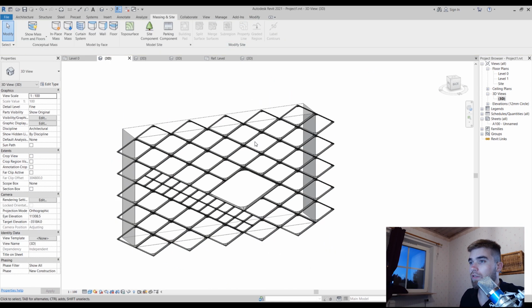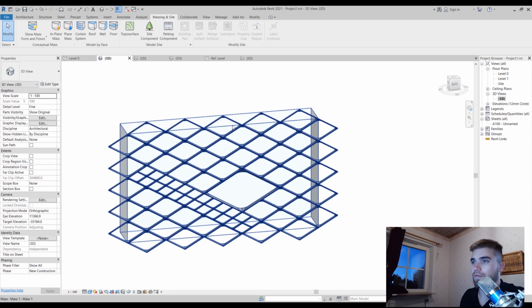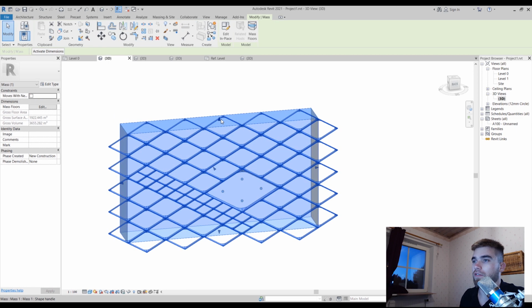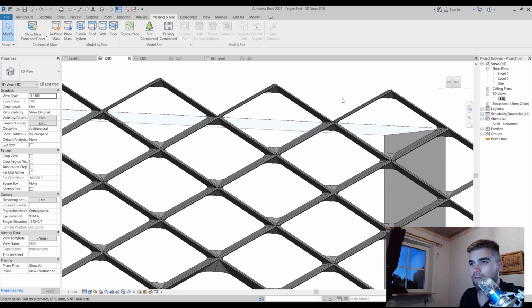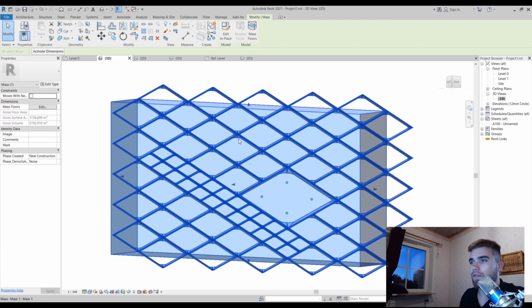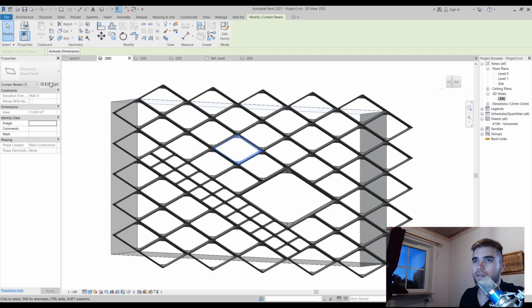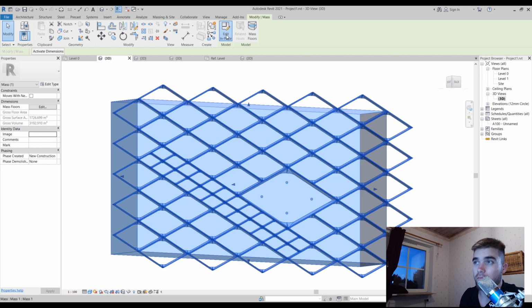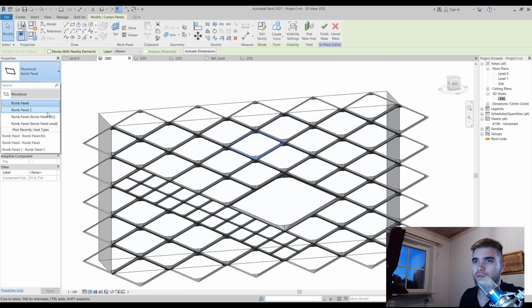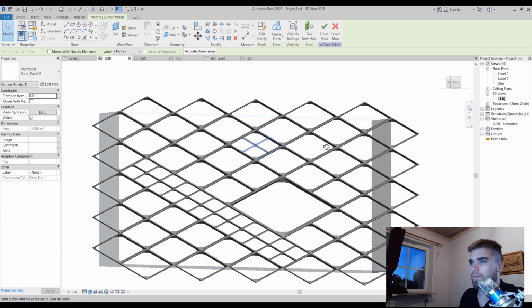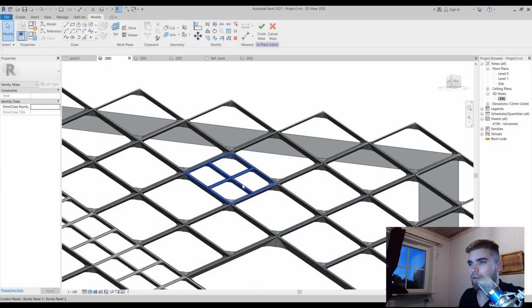So what do I mean that we have these changes? We can always go to that mass and just make it shorter, for example, and all these panels are going to adjust accordingly. And now I can actually go here, and to go here I have to click on edit in place first because this is a mass. And now I can select a different type of panel.